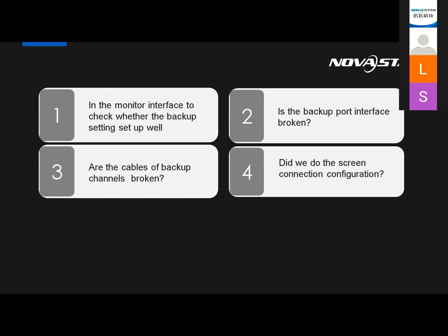The fourth one is, did you do the screen connection configuration? This is what I saw in one project. The customer asked me, Rob, why can't I get the backup to work? I logged in with TeamViewer and noticed he didn't do the backup screen mapping.